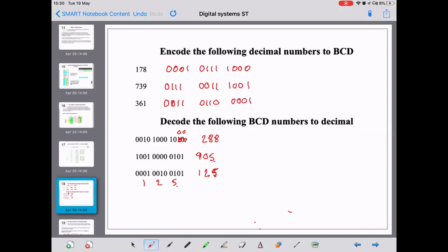Yeah, so that's binary coded decimal used in displays. Now, what would normally happen, because using BCD wastes some bits of storage, your computerized system would store the number as a binary number, convert it to a BCD number, and then display it as a code using a 7-segment display, because it uses less memory, and also arithmetic operations like plus, minus, divide, multiply are much easier to do on the actual binary number than on the binary coded decimal number.